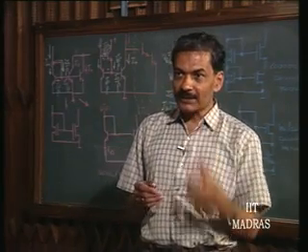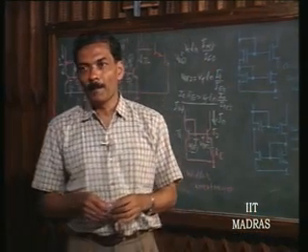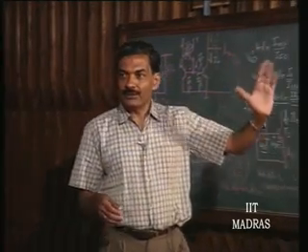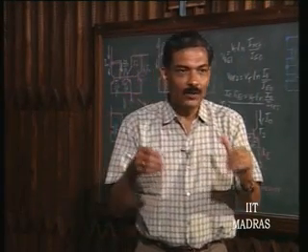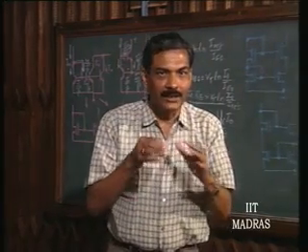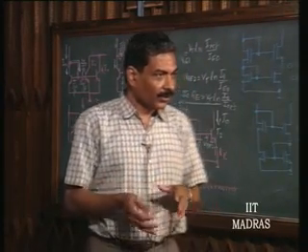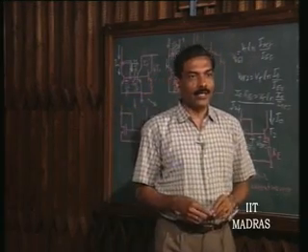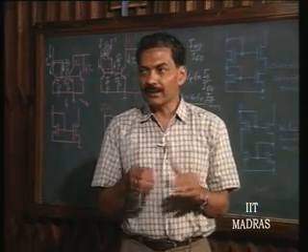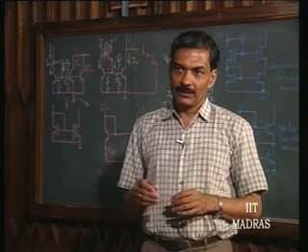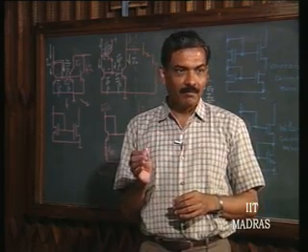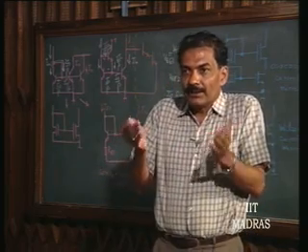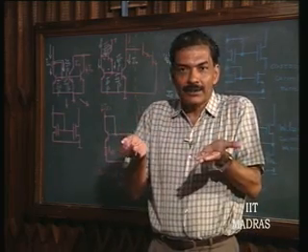The disadvantage of such a scheme is what? The output impedance is progressively decreasing. As you shunt the current sources, output impedance is going to progressively decrease. Okay. So, we will again see this particular principle reflected more efficiently in what is called the translinear principle. So, making the currents different by means of areas is another way. The current can be only multiplied. You can generate a current which is higher than the original current.